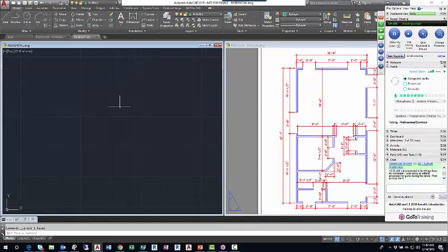I'll get rid of that. Now I'll double-click the mouse wheel. Click, click. That zooms me out as far as I can go. I've zoomed extents. And then I'll pan a little bit. So I've panned so I can see my UCS icon, the little XY symbol, and I've panned so I can see the red horizontal grid line. I can see the green vertical grid line. So I'm probably zoomed out just about as far as I can in this drawing.